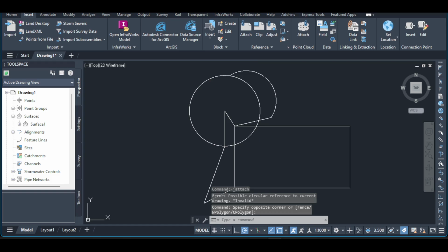When your settings look right, click OK. The selected DWG is now attached as an Xref. You'll see it appear in your drawing, typically as a single, uneditable reference. Its layers will come in with their original names, and you can control their visibility from your host drawing.